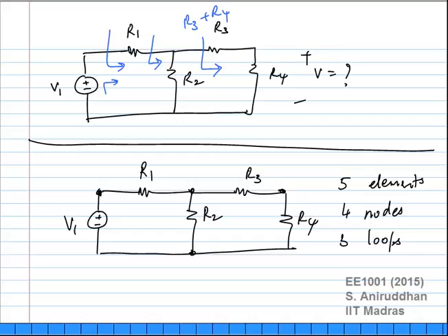Yes? Sorry, can you please raise your hand? Can't see. Yes. All the current will originate at that point. No, because you might have, when you talk about voltages, you talk about potential differences. So when you talk about KVL, I can understand, maybe you take one node as a reference node. Here we are talking about KCL. So there is no talk of reference nodes yet.